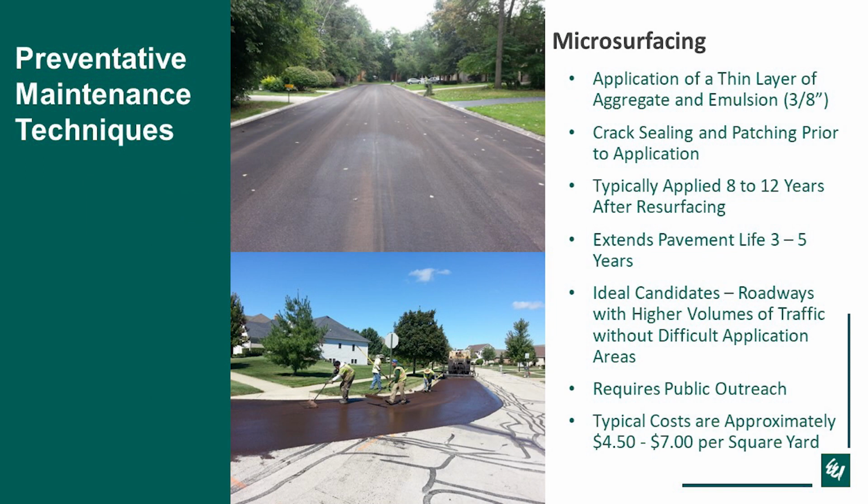Microsurfacing, it's another preventative maintenance option. It's typically done around the 8 to 12 year mark. You're going to want to crack seal and do any patching prior to doing this microsurfacing. It's an application of a thin layer of emulsion on the road,